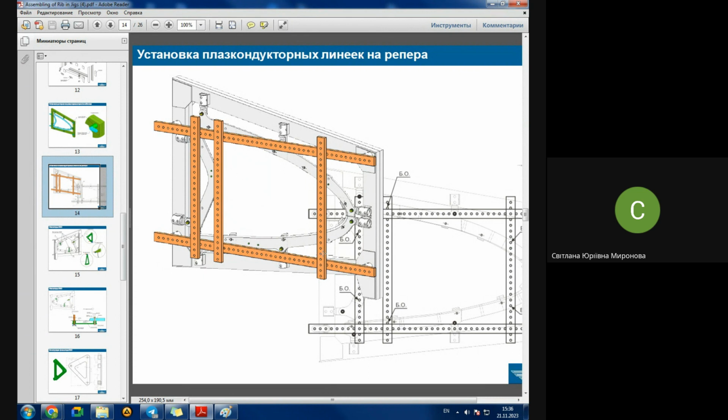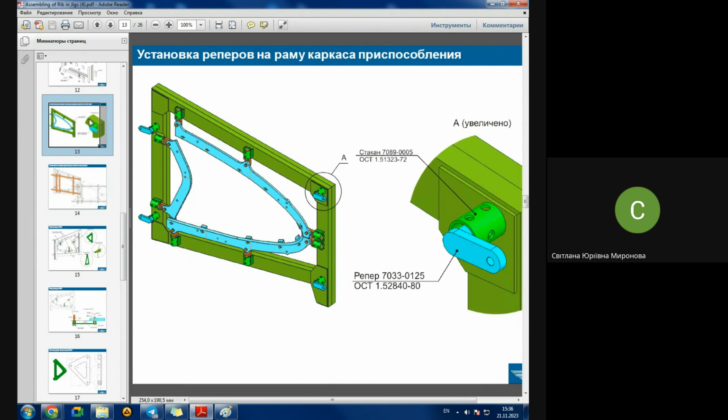How to find this first place? Well, when they are creating this coordinate system, those platforms, reference platforms, are necessary to keep the very first position of those rulers in the jig, in order that next time, while inspecting, you may place the rulers, your coordinate system, exactly at the same place.